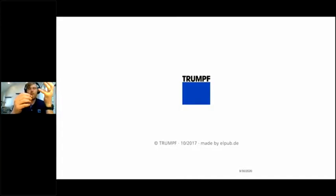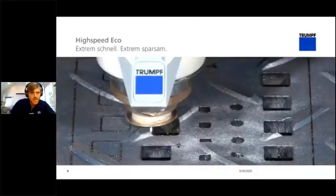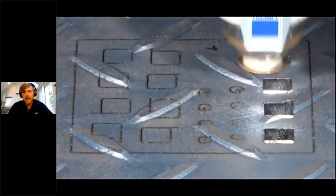The thing with the Eco, though, and what's really unique about it, is that it rides on a little cushion of whatever you're cutting with, so compressed air today or nitrogen in other scenarios. That allows it to be very flexible. Its normal offset from the surface of the material is about 10 millimeters or so. It is touching the surface of the material, but if the material is not flat, the nozzle can adapt. This video shows how it adapts going over checker plate, which is, I'd say, a pretty severe scenario.